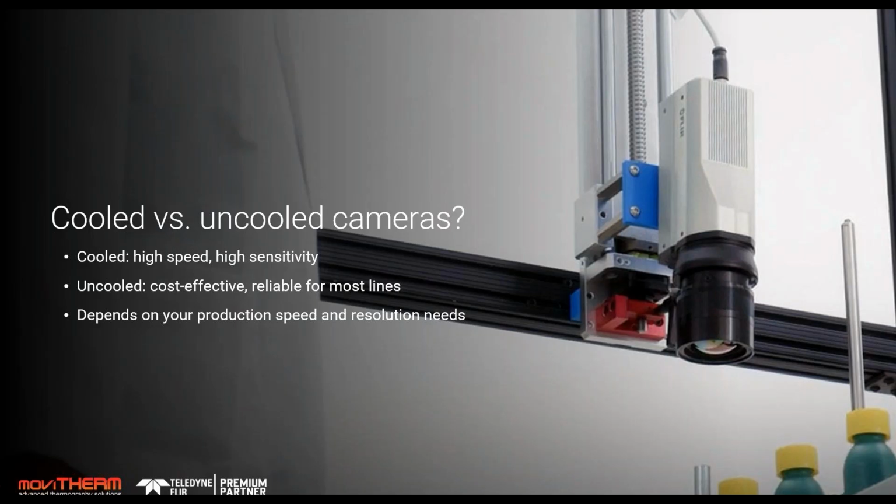So a little bit different. The IR radiation that's hitting the detector actually created some heat on the focal plane array, and they had a voltage that was being applied through each one of the pixels. As that heated up, it created a voltage change. And so it was a totally different type of technology. The result was the same in terms of the thermal image being produced, but we didn't need a cooler in this case.